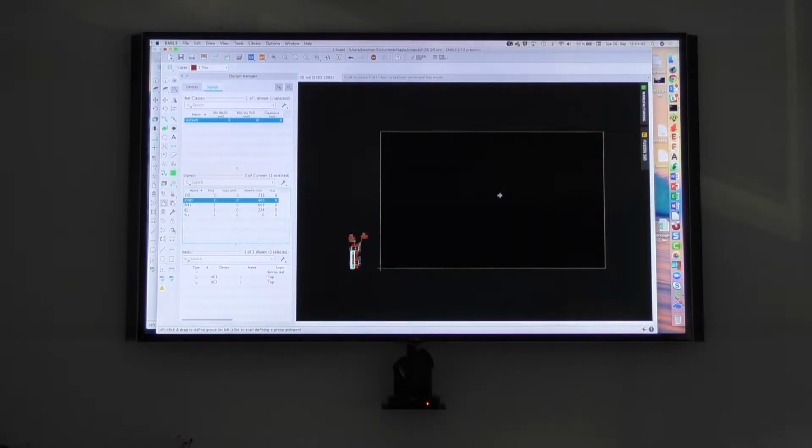Because if you have done all the design, and you see I have used the layer setup that works for me, and the board manufacturer says, okay, that's quite nice what you're doing, and maybe you have already a quotation, this board costs 200 euros for example, and you send it to the board manufacturer and they say, hey, what you are doing there is not our standard, we can do it, but you pay 5 or 6 or 7 times the price, or you change your design. And if you change the design, in most cases you start from scratch. And that's something you have to think about before.